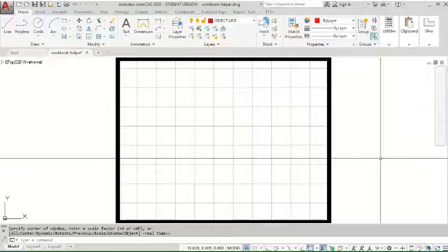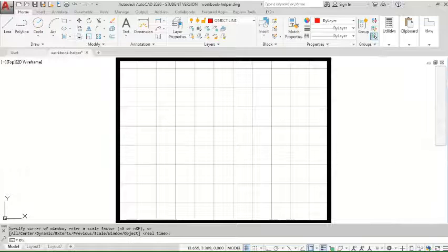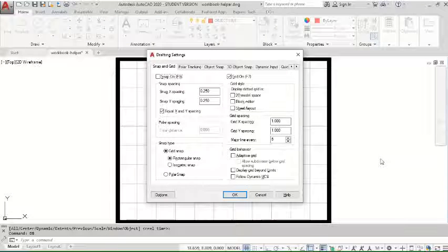Change line weight settings to inches for inch users and millimeters for metric users. Then adjust the display scale. So to get into those, you have to type in DS for drafting settings. And we want line weight and adjust scale. Oh, no, sorry.